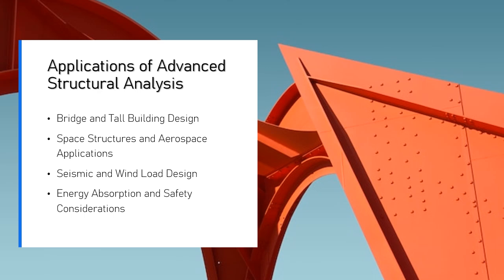Advanced analysis: Engineers used finite element analysis, FEA, to model the load distribution and stress concentrations across the wing structure. Tools like ANSYS and Abaqus helped simulate the dynamic response of the wings to aerodynamic forces, ensuring the structure could handle fatigue and impact loads. Stress tests were performed to evaluate the wing's performance under extreme conditions, including high-speed flight and landing loads.